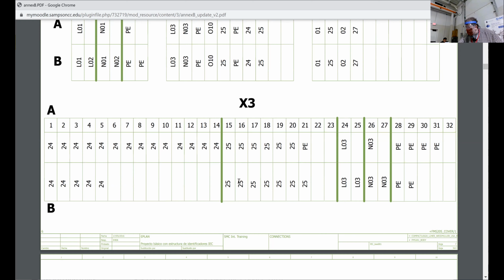And you have to physically look on the front of them. Whatever wire lands into a terminal this way, it's connected correctly. You look in front of it. And then there are actually some jumper clips that go in that make a lot of them common. It might be 10 or 15 of them that are joined together horizontally through a bus clip. And you can see that. I'll show you that when we get looking a little closer at things.